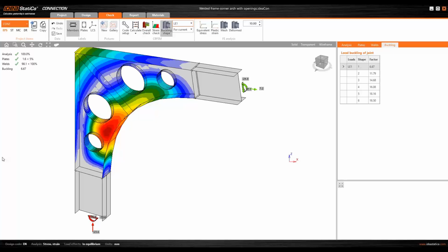Sometimes if you perform some more accurate analysis, like the second order analysis, then you can go a little bit lower with the factor. It has to be greater than 3, but it is really about knowing more about the construction, and so we provide the critical force factor, but the engineer has to decide if 7 is enough or it has to be greater than 15.